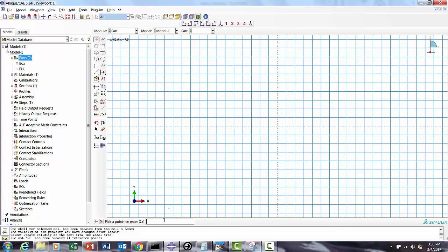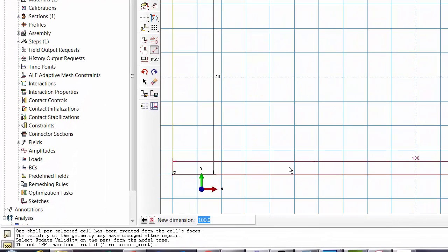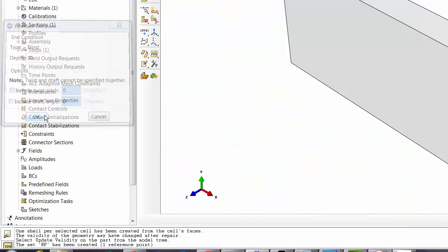And this liquid is partially filled, so I'm going to put minus 50, minus 20, and then 50, 20. So that way I can create something partially filled. I can see this point here, and this point is here. Okay, perfect. Let's check. This is 40, perfect. Is this 100? Perfect. And then extrude by 10. So I got one dummy.